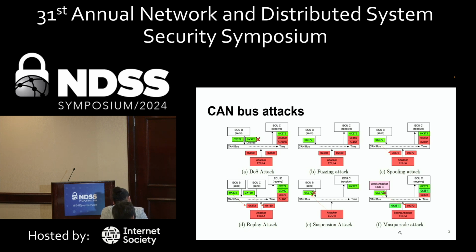In a fuzzing attack, a malicious node floods the network with a large number of frames employing randomly generated IDs and malicious payloads to mimic legitimate frames. This can include injecting valid IDs during normal traffic or generating entirely new random IDs. In a spoofing attack, the attacker targets specific CAN IDs to introduce malicious messages.